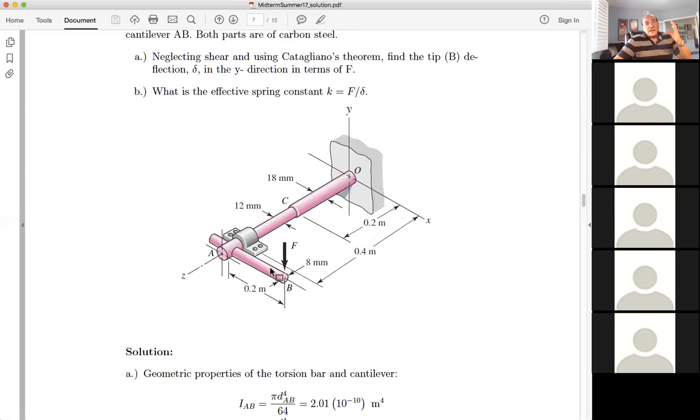But if we think a little bit carefully, as this shaft deflects, then the torque tube that is connected, which is stepped, will also have to twist. And when the tube twists, it has two sections, AC and CD. Each section will have to do some work, and when it does work, it means it's going to store elastic energy. So there is elastic energy stored here, elastic energy stored here, and elastic energy stored in bending.